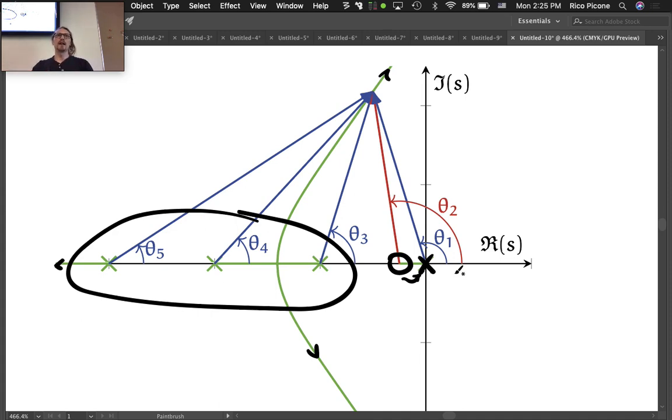You're going to get a slower and slower steady state error compensation the closer you get that 0 to that pole. And usually we don't want it to be too slow. Okay? So this is usually a trade-off that happens, and we'll talk about that trade-off. But that's the general method. It's actually pretty straightforward.